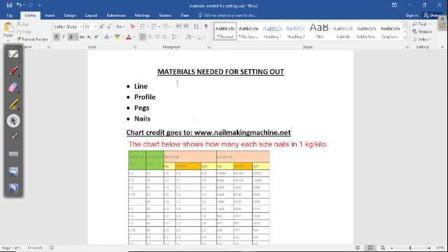The profiles are usually boards of 75 mm width, 1 inch thickness, and 3.6 meter length. Profiles are not sold in the market. They are converted from a full plank of 1 by 12 by 12 size, which is 1 inch thickness, 12-inch width, and 12 feet length. That will give you about a 25.4 by 304.8 mm by 3.6 meters board.